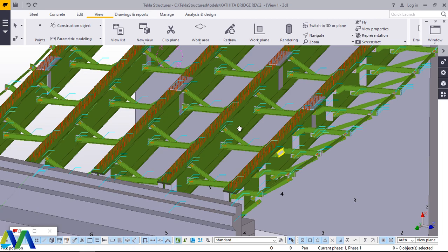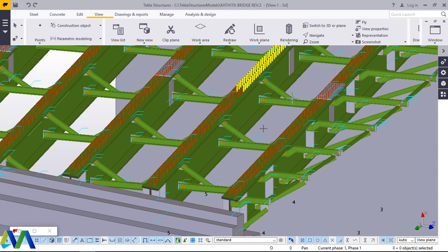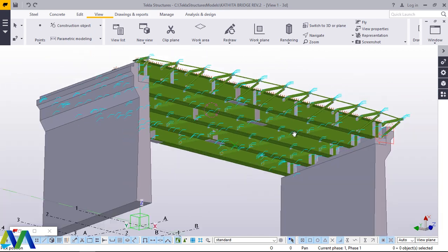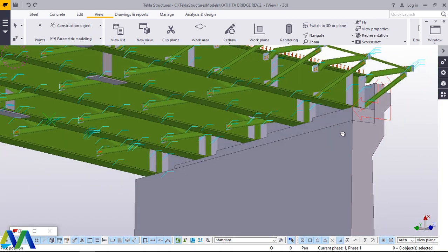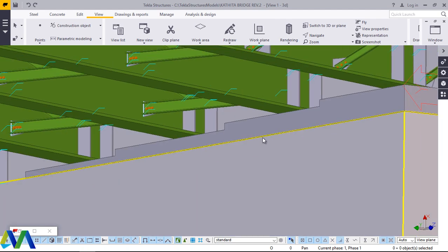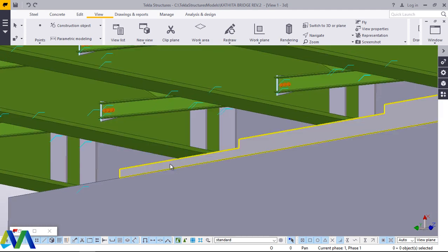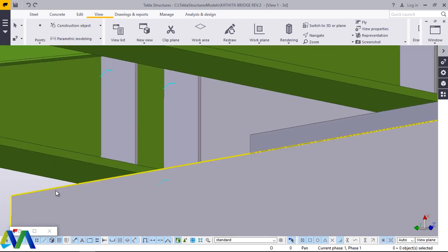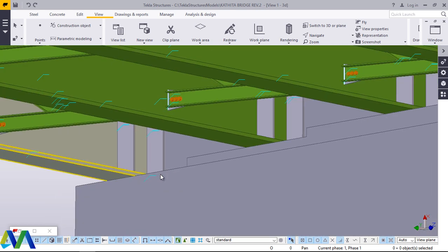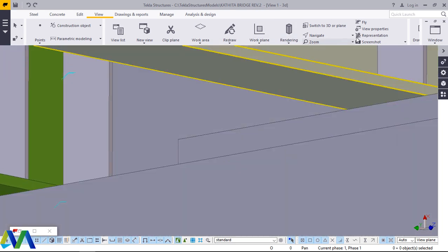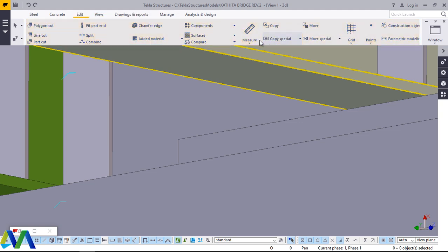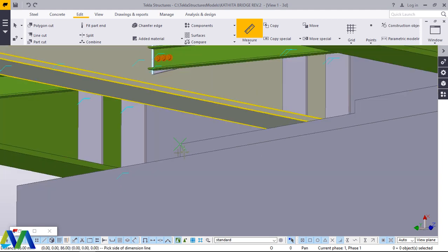Now this bridge, if you take a look, actually, the beams are not on the same level. If you go below the abutment, you'll see I have placed these steps. This was my reference level. They vary from, let me just show you the distance from my 0 level. From that 0 level, I elevated this from that spot to this spot by 86 millimeter.